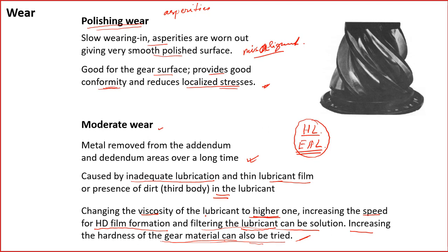Mhm. So we have to continuously circulate, but it is inside the case itself, right? Not like engines where the lubricant is collected in the sump and then filtered and then goes back. For example, in a car gearbox, the lubricant is continuously purged inside, but it is not circulated and filtered. So therefore, we need to change the gear oil after some time. Yes, sir, but it also limits our application, no, sir. Yeah, it limits our application.